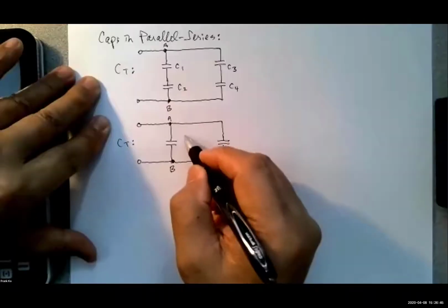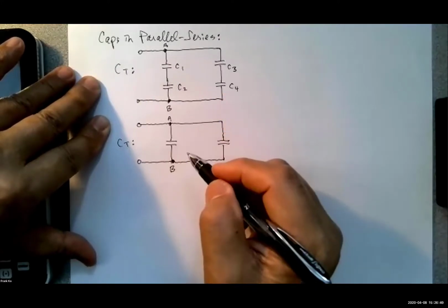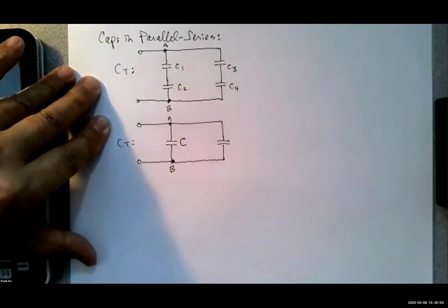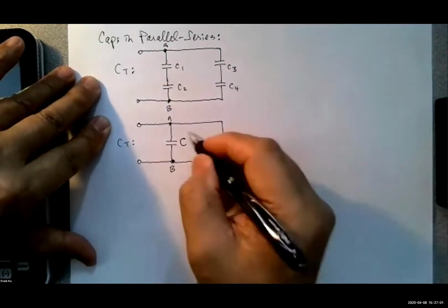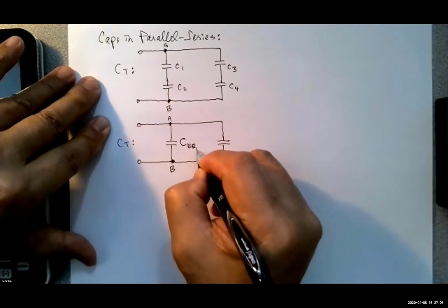In series, so that's the reciprocal. I would calculate it that way, but I'm looking for a label before I do any numbers because I didn't present any numbers yet. C1 times C2, a product over sum. Again, we would calculate it using product over sum. I was hoping you would call this CEQ1.